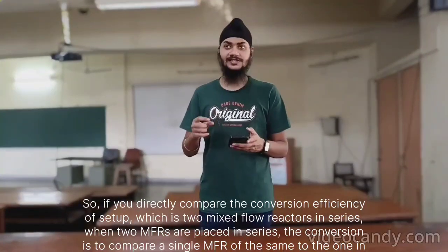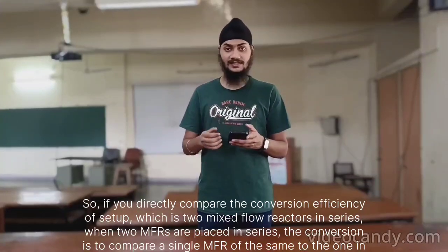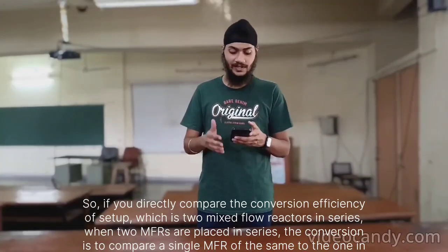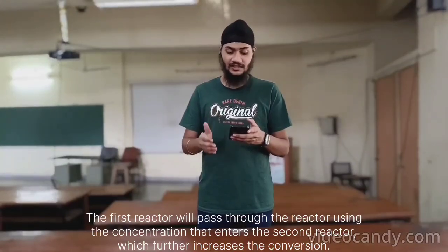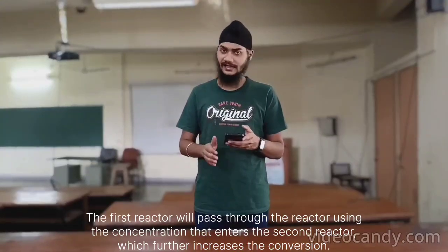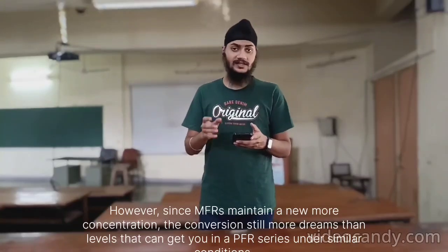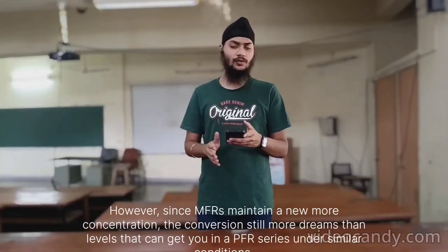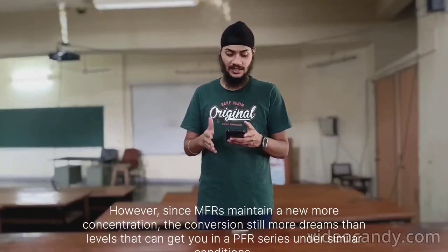The setup which is two mixed flow reactors in series. When two MFRs are placed in series, the conversion is compared to a single MFR of the same total volume. The first reactor will partially convert the reactants, reducing the concentration that enters the second reactor, which further increases the conversion. However, since MFRs maintain a uniform concentration, the conversion still won't reach the levels that can be achieved in a PFR series under similar conditions.